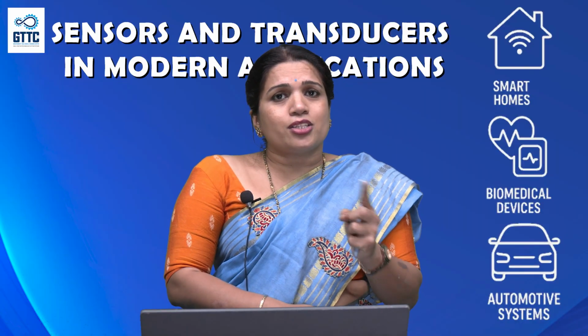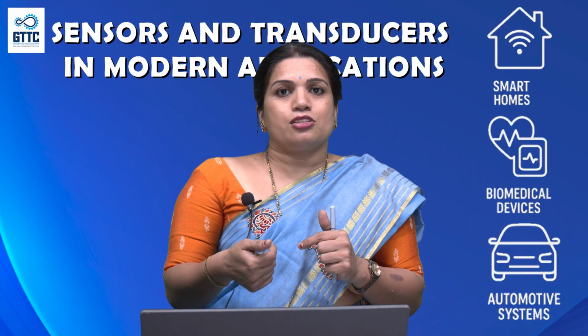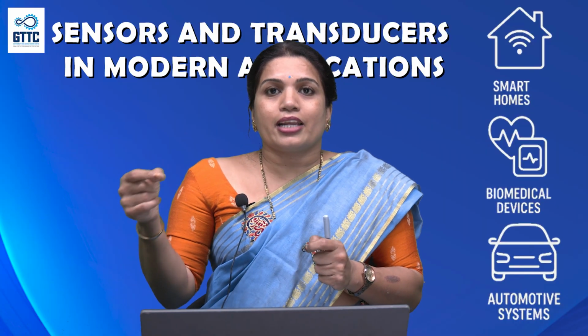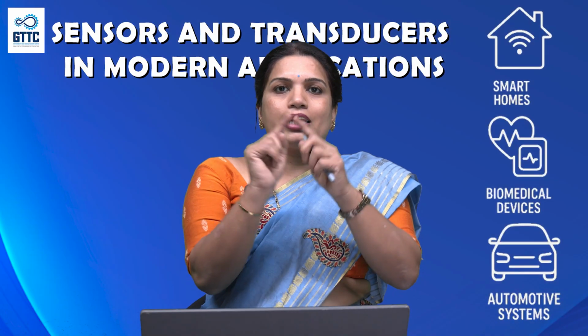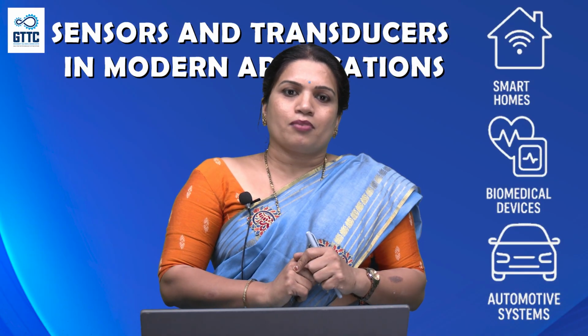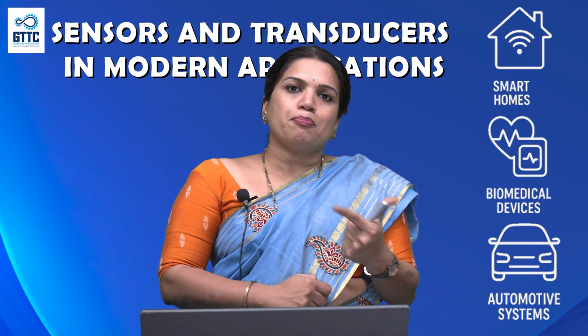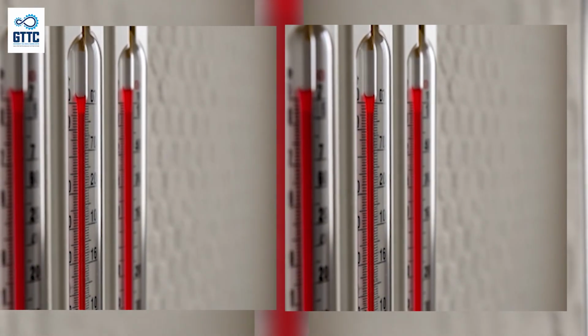Whenever the temperature changes, resistance will change inside the instrument. Whenever the resistance is changed, the electrical signal will give a different number in the output display. We have two types of thermistors, NTC and PTC. NTC means negative temperature coefficient.